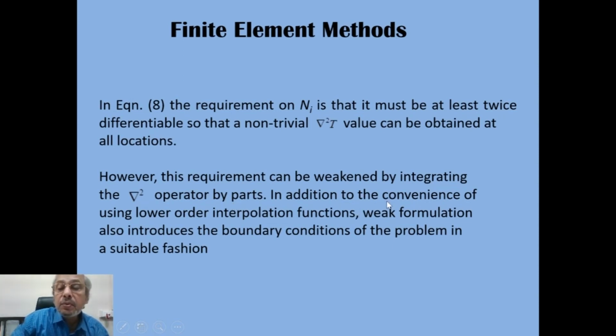In addition, this offers the convenience of using lower order interpolation functions. Also, this is called weak formulation because it helps us in implementing the boundary conditions naturally. The form of the equation becomes such that one term of the equation exactly becomes the boundary condition.